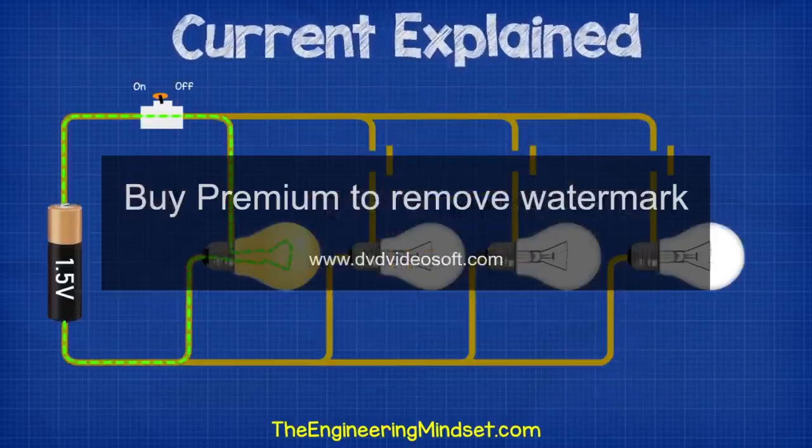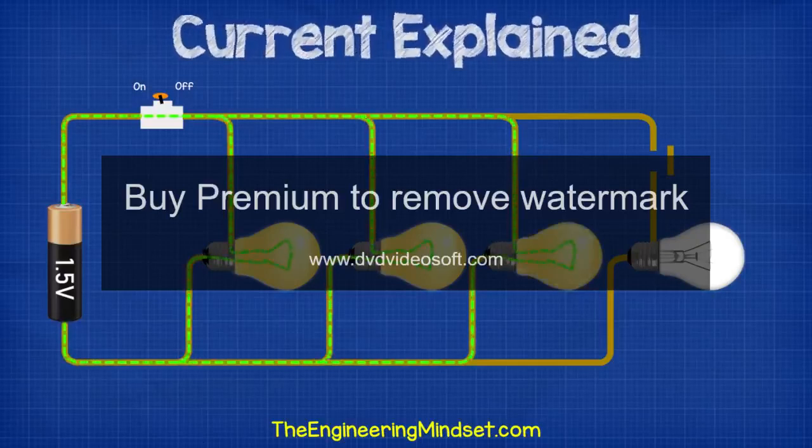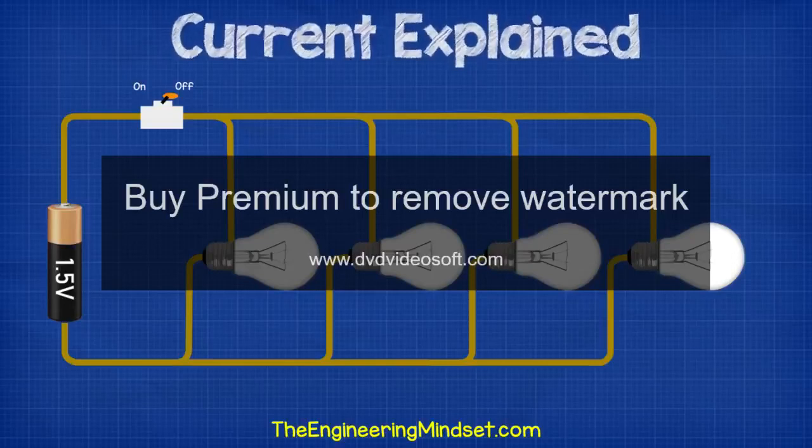If, for example, we slowly add load to a circuit, then the bimetallic plate will detect this slow rising current because the current causes it to heat up. As it approaches the design rating, it will break the circuit to cut the power and protect the cables and devices. The load can then be reduced and the circuit breaker reset, unlike a fuse.